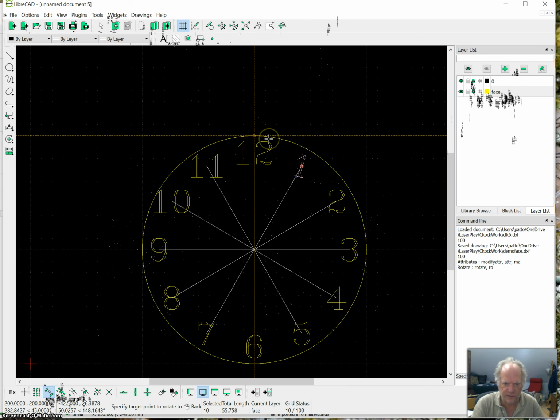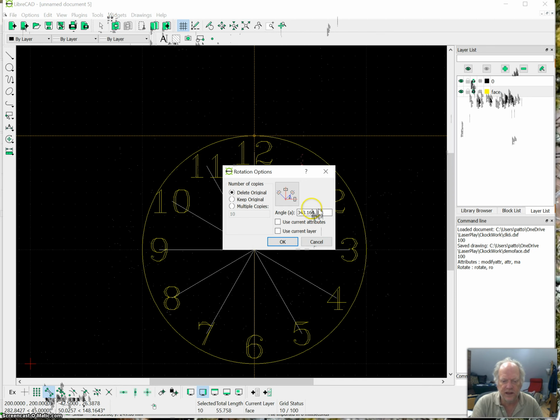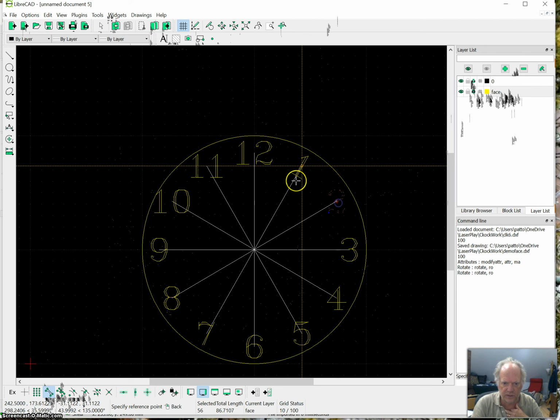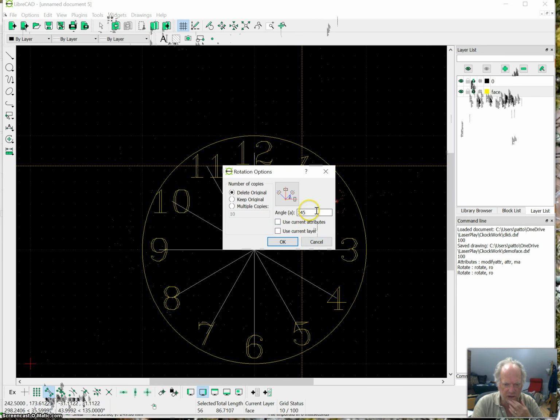Okay, I should be able to figure this out exactly, but you'll have a chance right here, because what I can do is say, oh wait, I gotta rotate this 330 degrees. Remember, it's going to be in increments of 30, and voila, now I've got that perfect. So I go here, and I'm going to right click. So rotate was one of the last things that I did. I'm going to choose that as my reference point. I'll choose the 12 as my turn point, and I'm going to click, and then right here I'm going to make this 300.